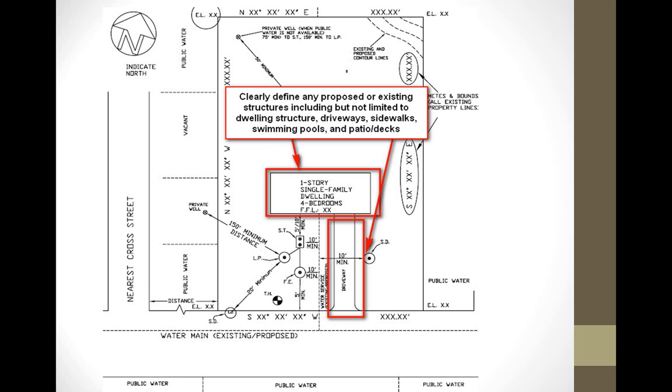Floor plans must also be submitted for all structures on the property. Clearly label each room as to whether it is existing or proposed. You should also show any unusual site conditions that may affect the design or operation of the sewage disposal system or water supply. These conditions include swales, bluffs, hollows, or slopes in excess of 15%.